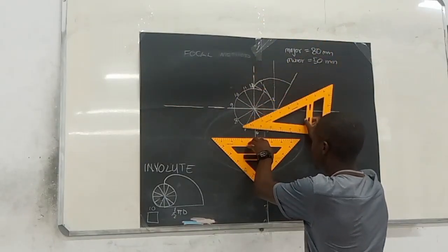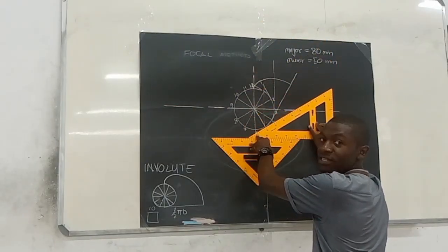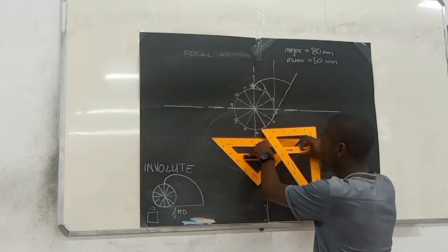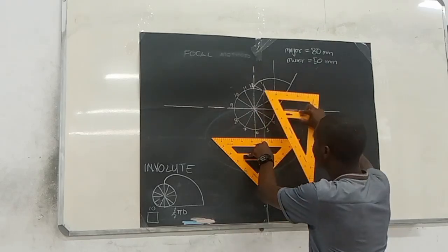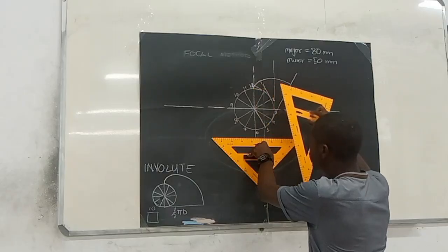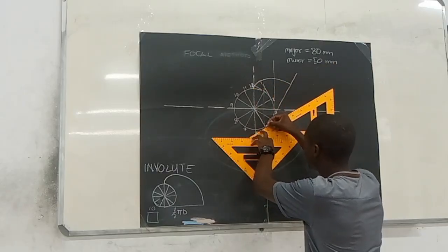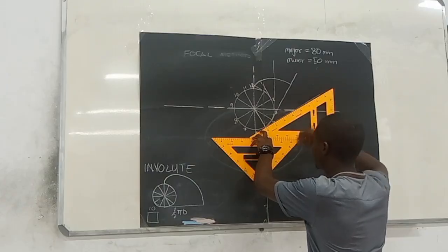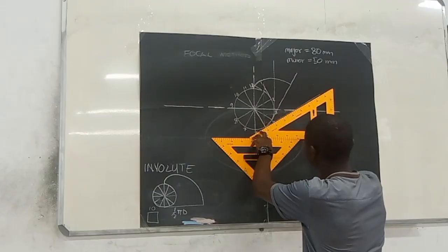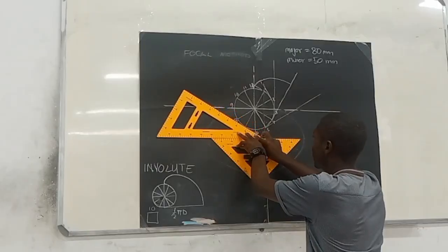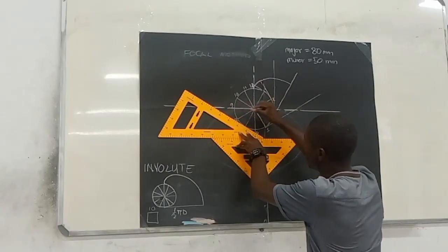For example, I rotate at point 5, I'll have a 90. Or even when I'm just like this on the T-square, you can see that I have a 90 at 6 and I have a 90 at 12. So we'll make use of that for us to be fast. So at 5, I won't start moving all that. I'll just do that. I want one at 7. I'll just rotate my set square until I have something that looks like a 90.